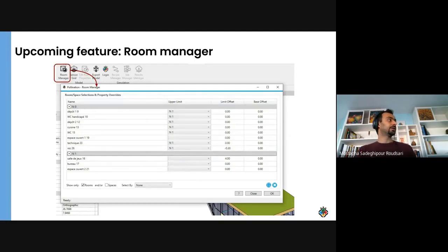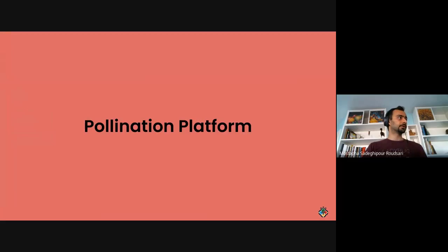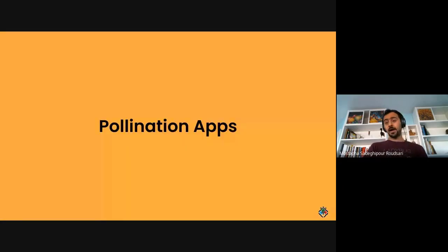So Room Manager and export model are two different things. Room Manager is for getting the stuff fixed in Revit. So it's reusable, so you don't have to do it every time on HB.json. Export model is the one that takes those and makes HB.json out of it, or df.json or GBXML based on what you want to export. And something that I said we're going to show today.